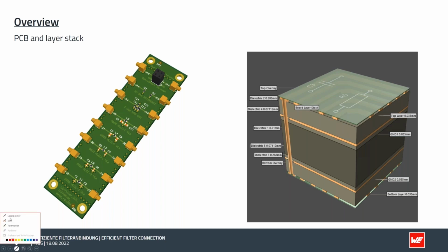I show you with the laser pointer here. With this constellation in parallel of the filter components, or in a typical pi structure, also some smaller components in 0603, and how it looks for the attenuation of the complete filter and what happens.